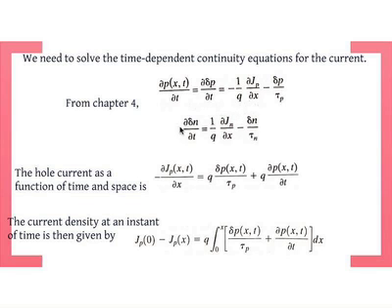The same thing for electrons. Pretty much the same equation, except that now the charge of the current is different, because electronic charge is negative, so the current is the opposite. Now, of course, to solve this equation, we have to solve this in both time and space. So if you recast that equation, this is the whole current. It's a function of space and time. Its space derivative is given by this term, which is the recombination term, plus the injection term, essentially. This is what I meant by the total rate of change of charge carriers. This is what's getting injected from the inside, pretty much.